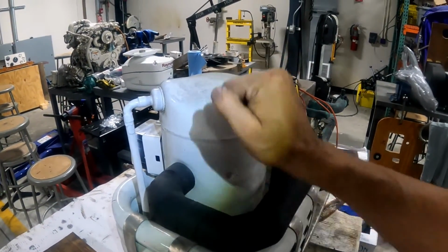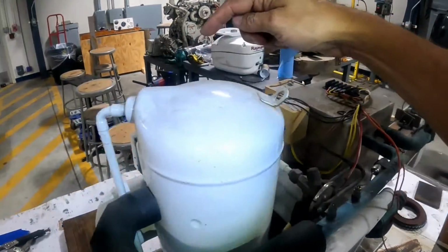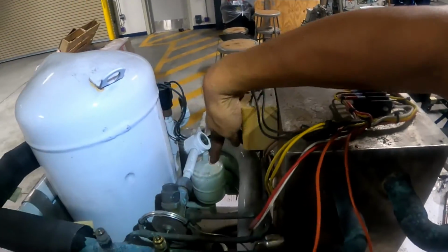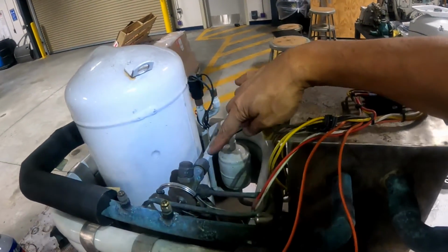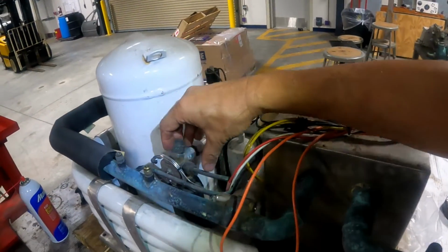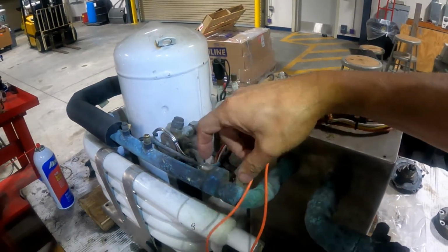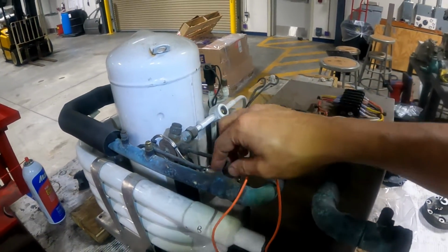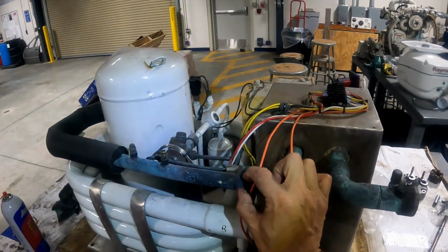The compressor compresses the refrigerant and sends the refrigerant out with high pressure. The refrigerant passes through the accumulator. The refrigerant right now is liquid with high pressure and high temperature, and passes through the expansion valve. The expansion valve opens and closes depending on the signal. The signal is coming from this bulb, and this bulb is touching the pipe, the external pipe, with refrigerant internally.